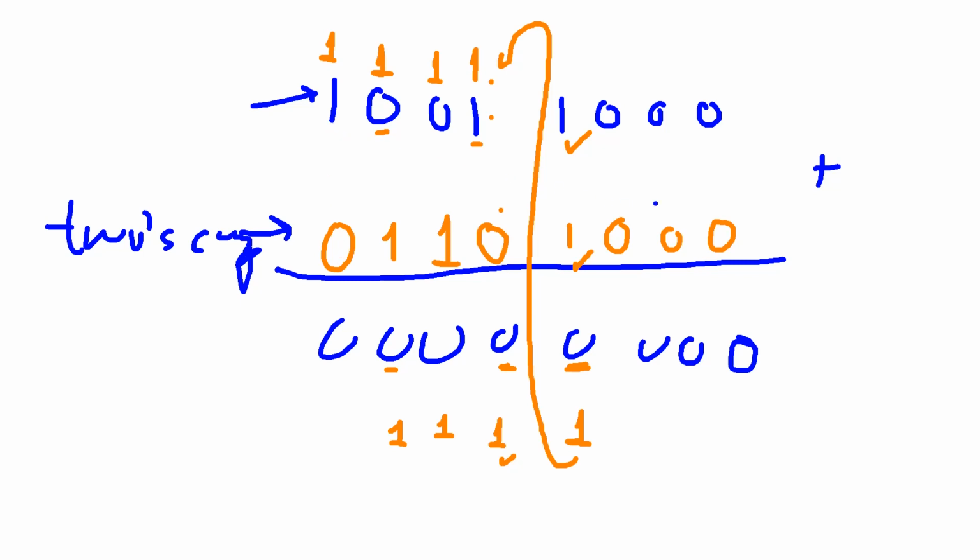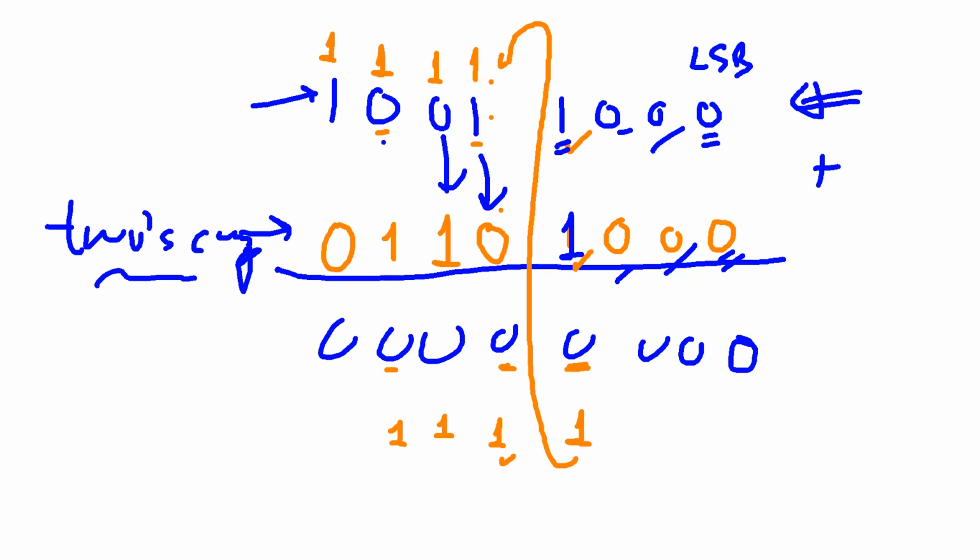So you know that to find the 2's complement of any value, you calculate from the LSB. If it's 0, the result of the 2's complement is 0, 0, 0, right? And for the first digit 1, it's still 1. But after that, it's the opposite, right? 1 to 0, 0 to 1. Because after this, for the addition, every bit has carry in.